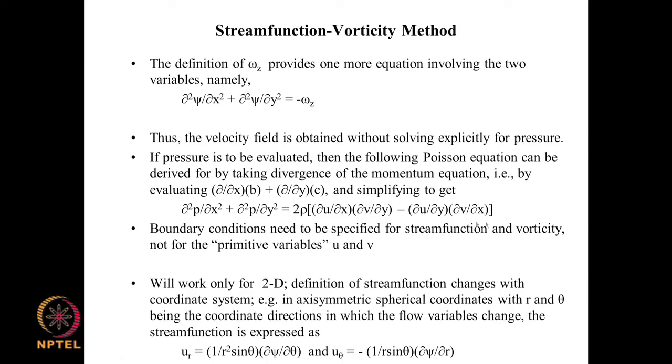And what is good about this equation is that it is like a Poisson equation, and by the time you have come to a solution of p, you already know u and v. So you can evaluate these things. You can evaluate the right hand side, and then you use finite difference approximations for this and this, and you can get a pentadiagonal matrix for p, and then you can solve it to get pressure.